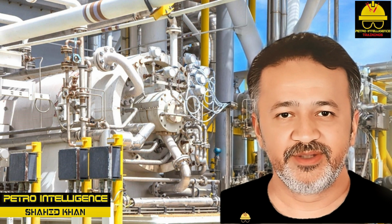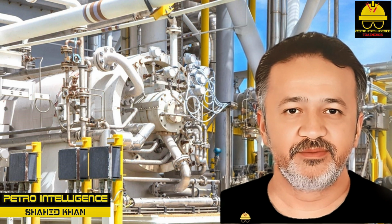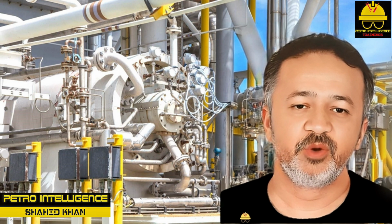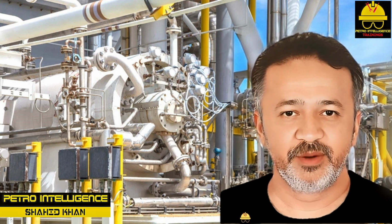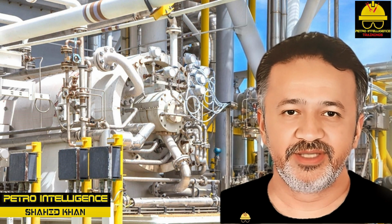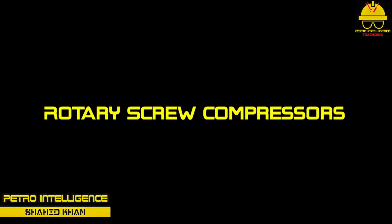Rotary compressors. Rotary compressors take their name from the rotating motion of the transfer element. A good case could be made that centrifugal compressors are rotary. Centrifugal compressors do rotate, but they do not positively displace or compress the gas. In contrast, the rotating elements of a rotary compressor displace a fixed volume of fluid inside a durable casing on each rotation.